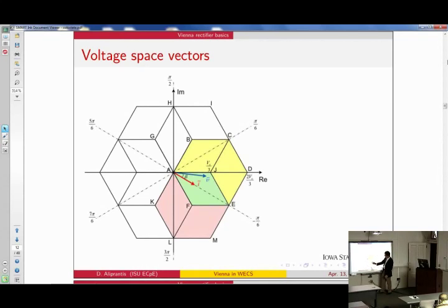If the vector, as it rotates, passes the minus 30 degrees and is anywhere between minus 30 and plus 30 degrees, in this range you can only use this yellow hexagon. Okay? So you switch hexagons. It has 6 hexagons that you can use as you go around.